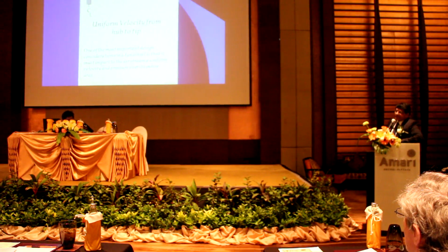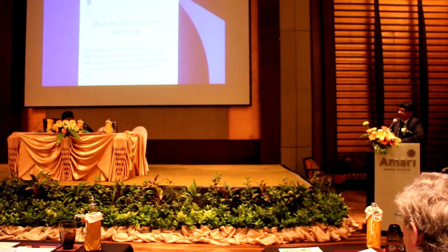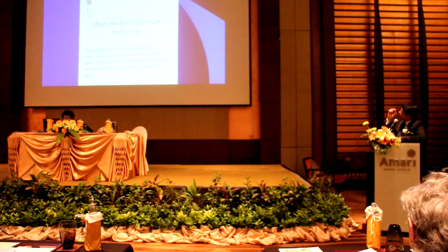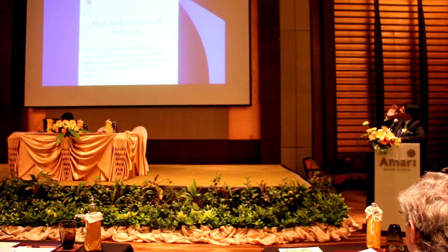This is a specific thing which actually decides how far away your ideal blade design is from the thing that you're actually operating. Ideally, what we need is a very uniform velocity along the length of the blade that you can see. The central darker portion is the hub, the other portion is the blade that you see. But in practice, you can never achieve this absolutely theoretical uniform velocity.